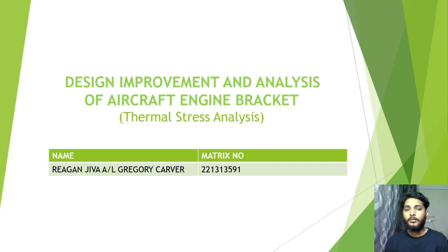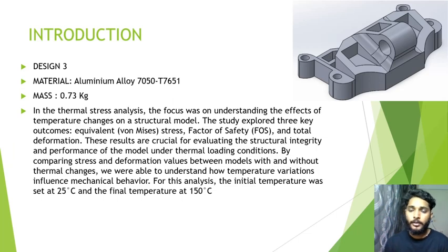Ikman Isha. Today I'm going to present this project about the design, improvement and analysis of an aircraft engine bracket. My part is thermal stress analysis. In this project, we have drawn three types of design, and the design we chose is design 3. This design was done by myself, and the material we use is aluminum alloy 7050/T7651. The mass of this project is 0.73 kg.